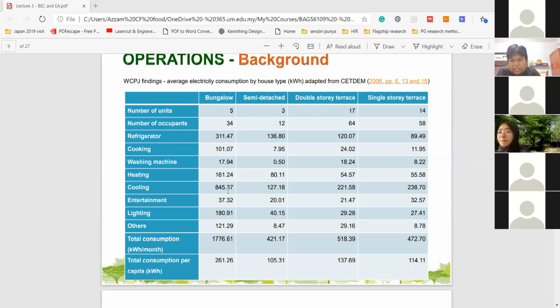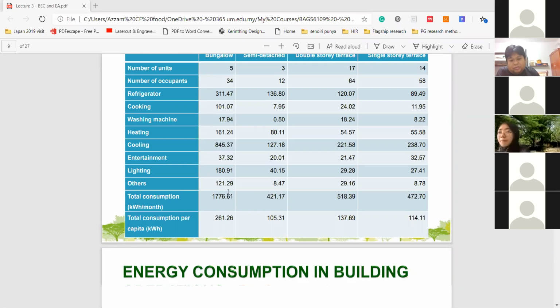So for us, at least as an indication, when we design something, you design the building and make sure that it's cool enough on the inside, insulated, with a good amount of ventilation, and then at the same time, you provide active systems, aircon or ceiling fans, whichever are energy efficient. That would surely limit the amount of electricity consumption.